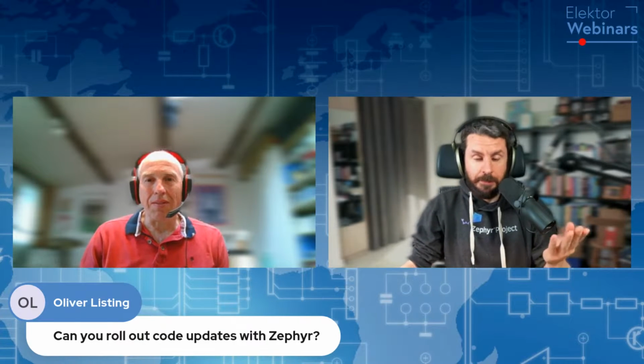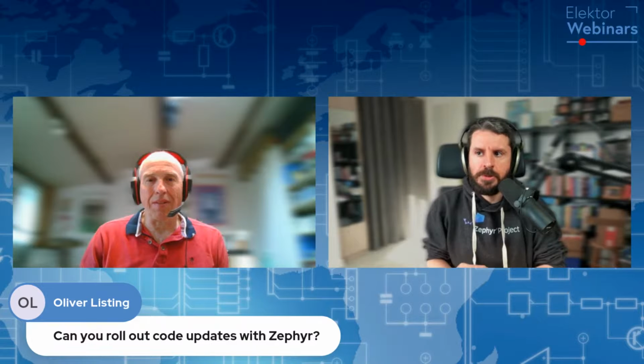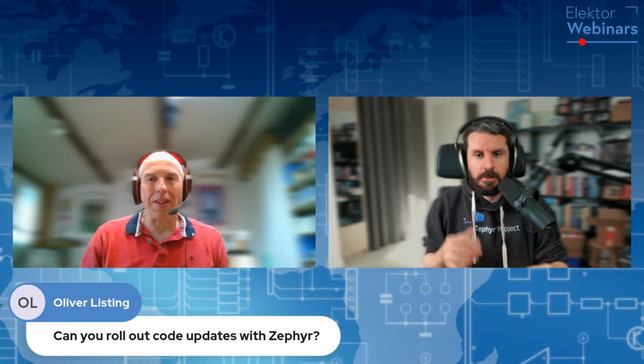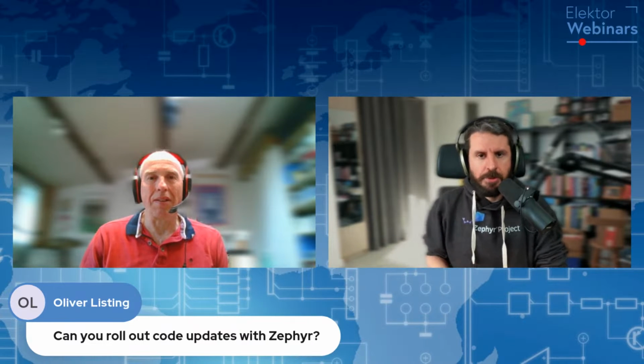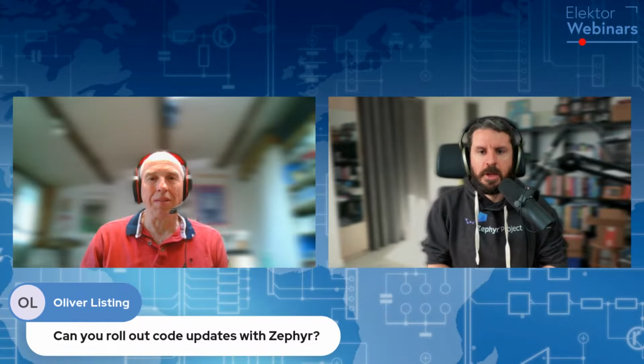And MCUboot would also allow you to do firmware upgrades using Bluetooth Low Energy, if that's something you're interested in. I'm sure some of you have played with that, right? From your smartphone or whatever, you press the reset button for 2 seconds, or whatever, and then you put the device in a specific DFU mode, and you update it that way.